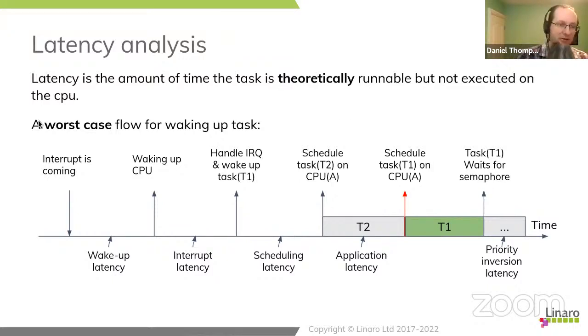And that roughly means that the interrupt has happened. If we are in a low power state, there might be some delay before we can switch into normal running state. By the time we're in normal running state, there is some intrinsic hardware interrupt latency of how long it takes us to react to an interrupt. And there's also potential for latency caused by interrupts being locked. So if interrupts are locked, we might have to wait a long period before we can start our interrupt handler.